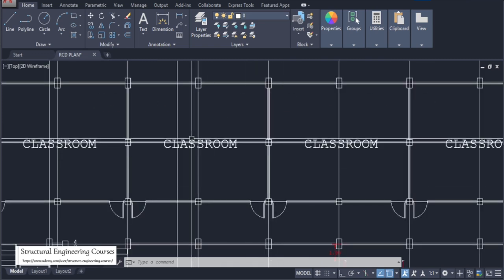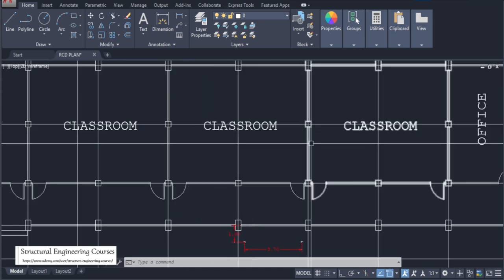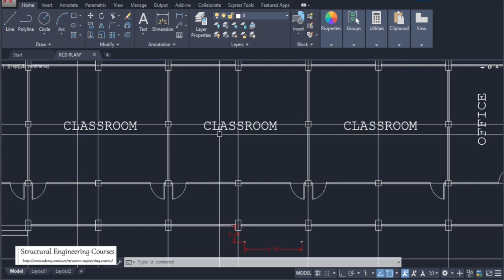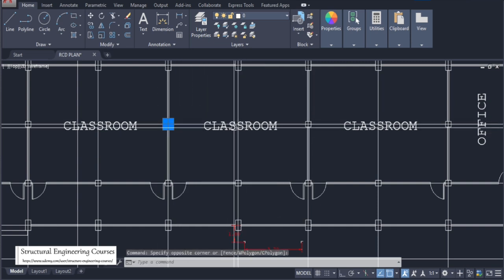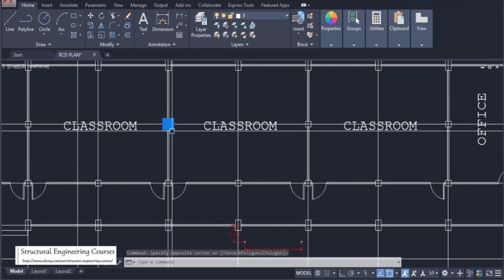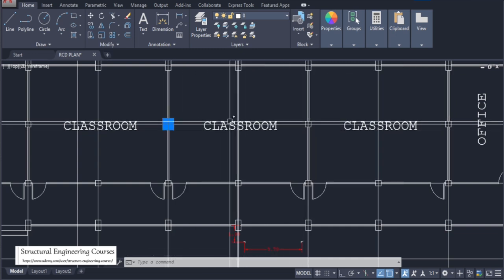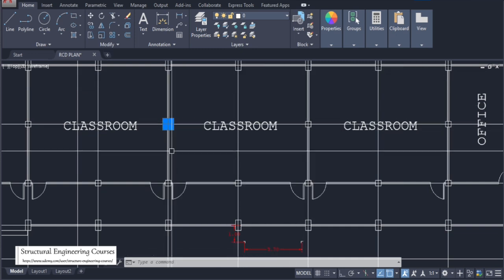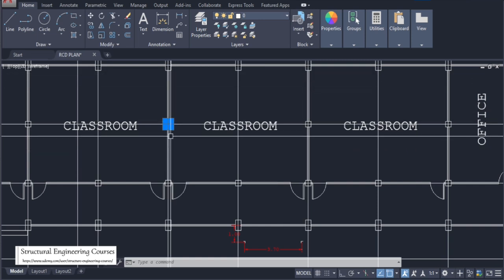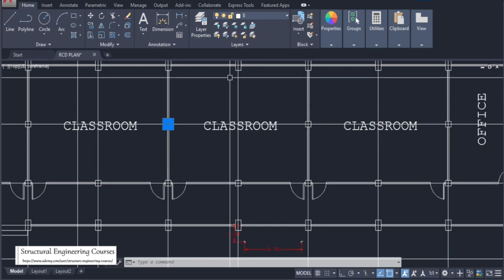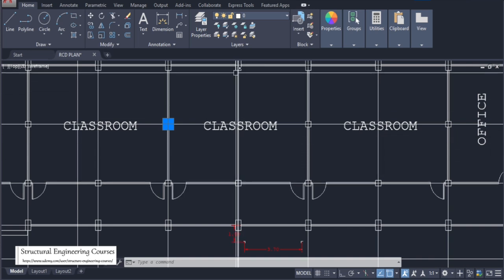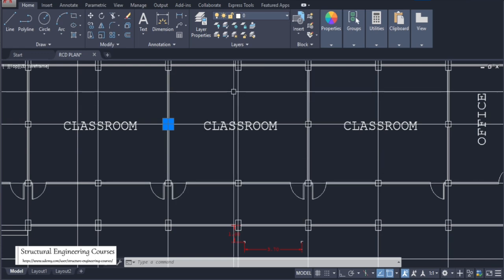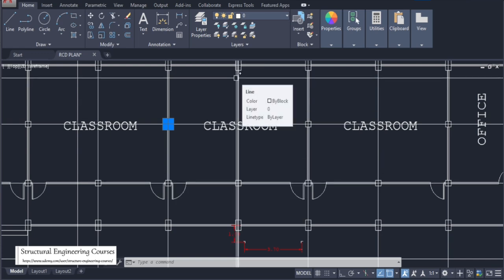So here we have targeted the alternative approach, as I had discussed with you earlier also, that our column should not come inside any room or inside any corridor. So we are not providing any column here. That is why the spacing of this is in the range of 7 meters. If we are providing a beam from this point to this point, this beam shall be lightly reinforced and smaller in size, but this beam needs to be somewhat larger in size, and reinforcement shall be higher on both the positive ends as well as on the negative ends.